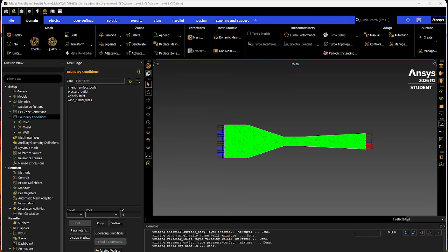So then if you put that in your calculator, you do 6 divided by 22. That gives you that, and then times 14.5622. So that gives me 3.9715, which is what we're going to put as our inlet velocity right here. So we're going to click on that, and then we're going to click edit.